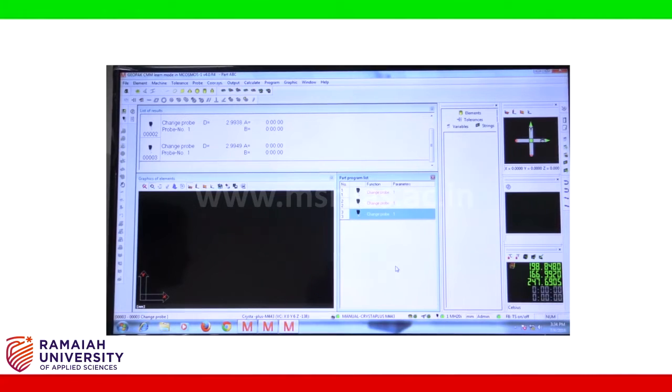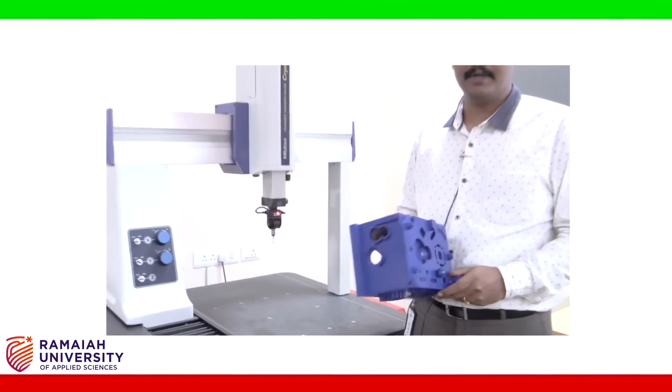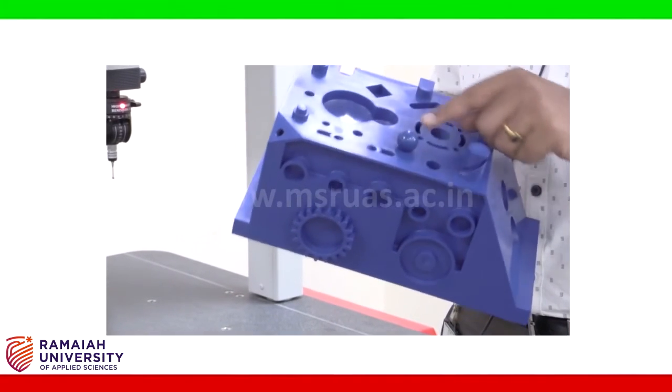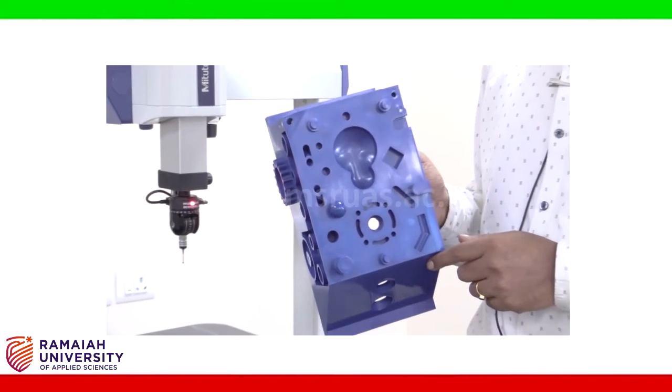Now before getting into the measurements, let us understand the accuracy and precision of the instrument. The accuracy of the instrument is minimum 3 micrometers, and it depends upon the length of the measurement. The precision is about 0.0005 or say 0.5 micrometers. Now let us start measurements. This is a model component. It is an injection molded component. One can see different types of configurations or different types of geometries on the surface. You are having a cylinder, you have a sphere, you have a cutout section like this. So all these dimensions can be easily measured in this CMM.